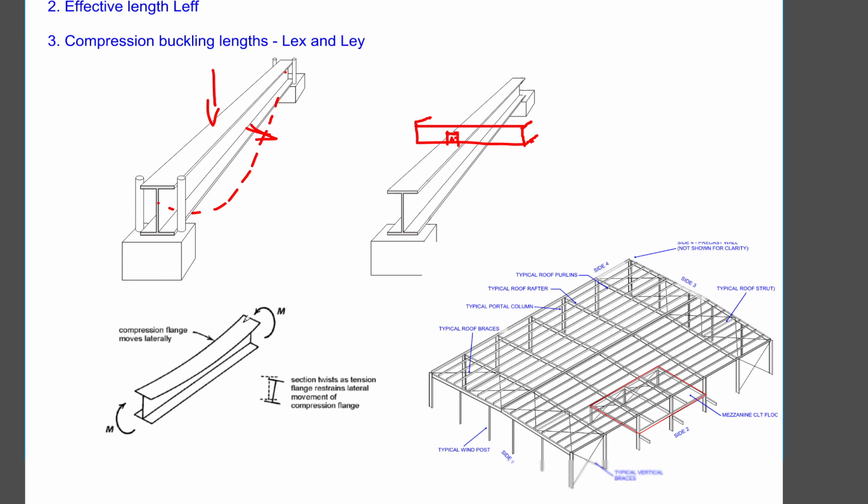It's so flexible in terms of the section because that's something to do with the shear flow within the I section. The shear flow is coming through, and coming down, and coming back up, and again. So this shear flow creates a load path that is trying to twist the beam. If you compare that with a hollow section, the shear flow creates a uniform load path that is very consistent in all directions.